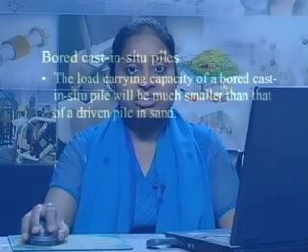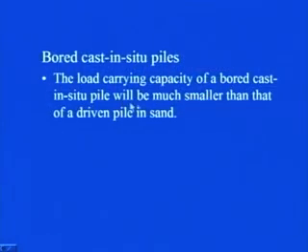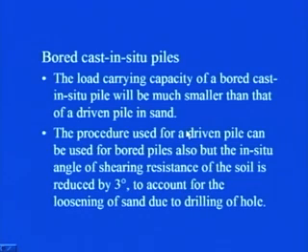So, in that case the active condition is generated, and the value of K becomes very small compared to the value of K in the passive condition, which was relevant in case of driven piles in sand. That is why the load carrying capacity of a bored cast in situ pile is much smaller as compared to driven piles in sand.